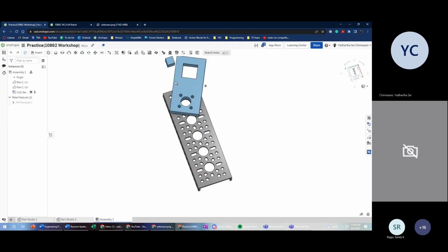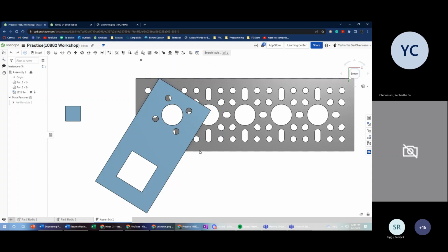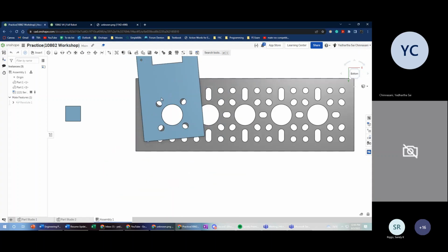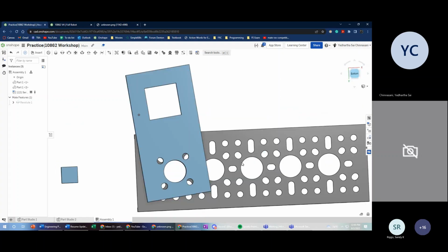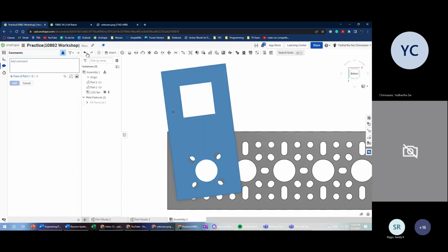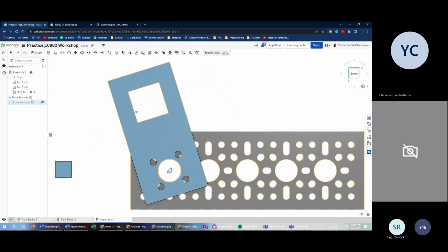And this is why a Revolute mate is something I'll just use to make your robot look cool. Like it really doesn't matter if you use this mate or not. You can just fasten it. If you know that it's going to be in a certain spot at a certain angle, just fasten it so you don't have to worry about it rotating and stuff like that.